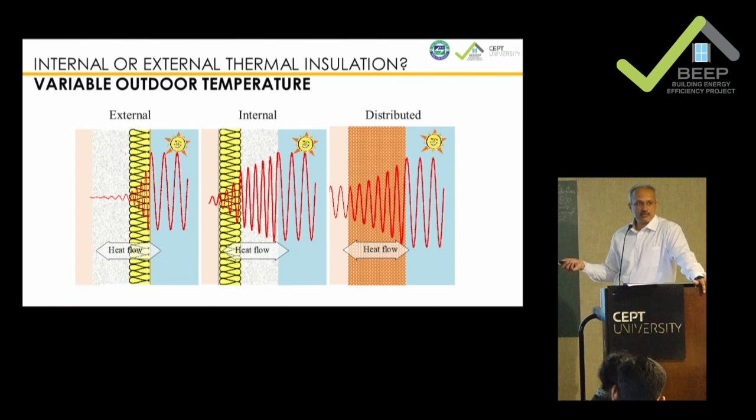Now, when it does not, and when outdoor cool air is coming in, if your wall rejects a lot of heat when your windows are open, when you close them, immediately you don't need to start your air conditioner, because your surface temperature would be low for an extended period of time, and then internal loads will start acting. When they go beyond some point, then onwards you start using the air conditioner. In that case also, your internal mass will be very, very important, right? How much heat can it reject in the night time so that during the daytime it helps, okay?